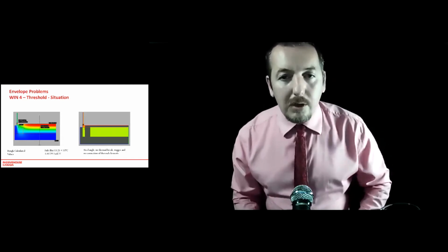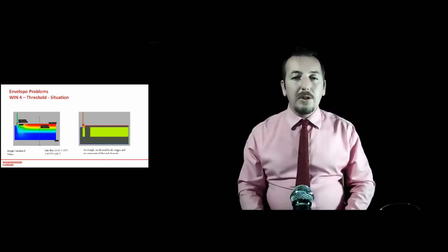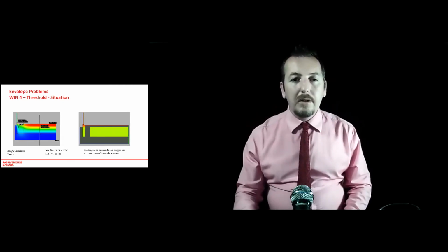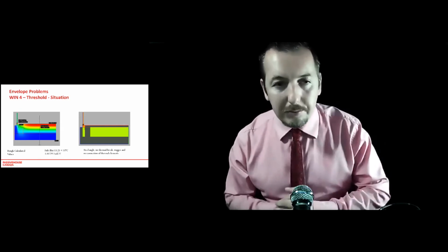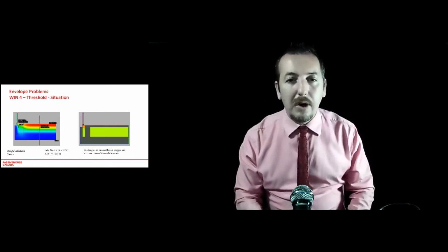Thresholds, although of small magnitude normally, are an important detail in terms of condensation. This one was pretty bad. It was 1 watt per meter Kelvin. So it's right out of order. And it was basically held up by steel. They had a thermal break. They insulated everywhere, but they didn't insulate this piece. And it was super bad, super bad. And the same cost to implement it correctly.